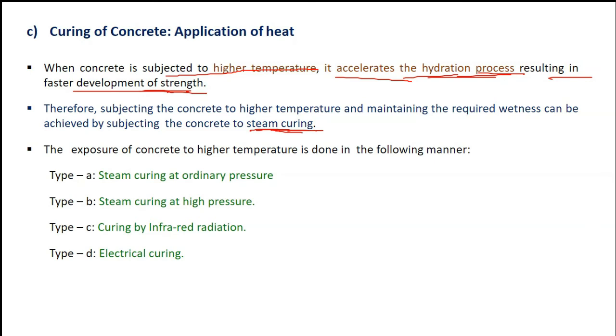When you cook your rice in the cooker, the rice is being cooked with the steam, right? In the same way we are going to heat the concrete by using steam. By using steam for heating the member, the water is not going to come out from the concrete, because steam has moisture itself, right? So the concrete is going to be wet, and at the same time, concrete is going to be heated.